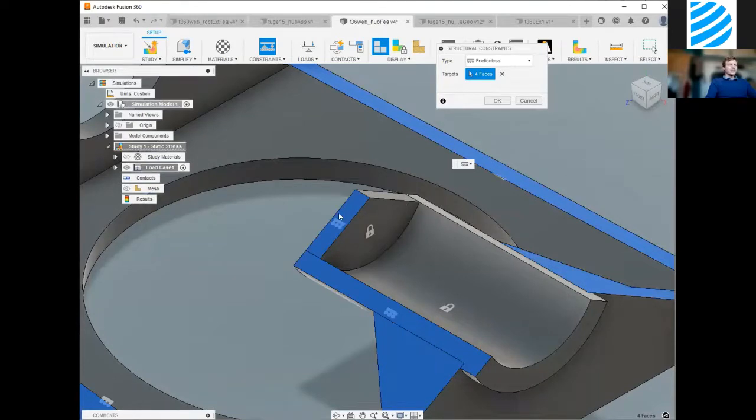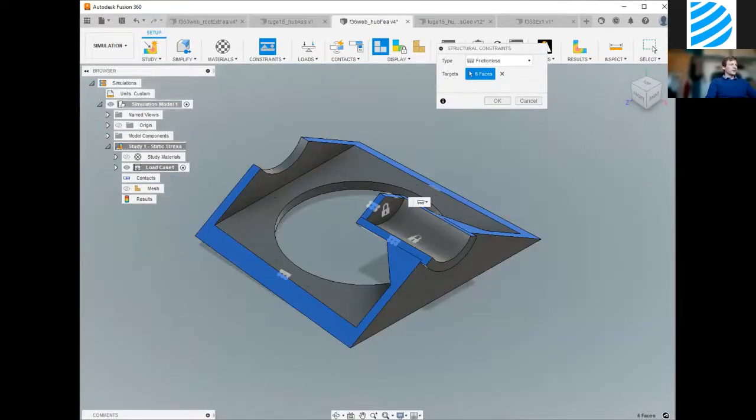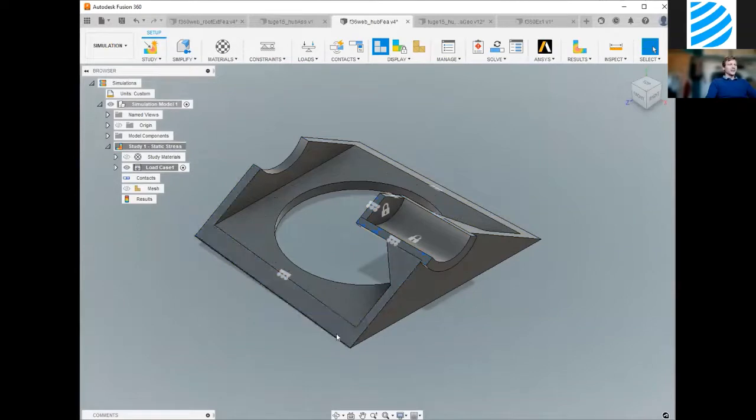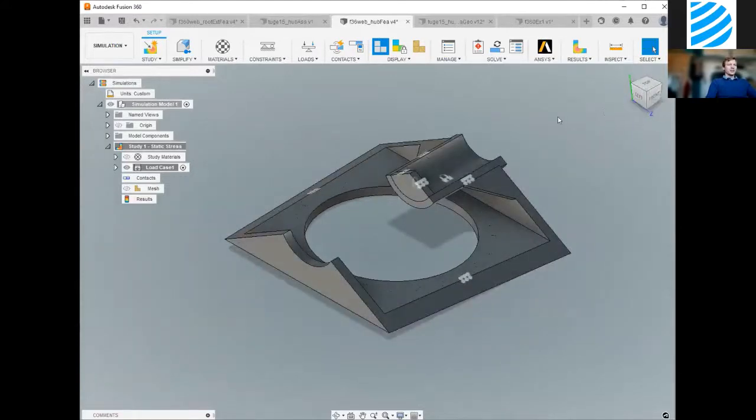What a frictionless constraint does is it prevents the surface from moving or deforming in the normal direction relative to the surface, because obviously there would actually be material there. It would be continuous all the way around. So this takes care of that. And beyond that, you would just follow the same steps we already followed with the other one, so I don't think I'll repeat that. I think our timing is pretty good now. And at this point, I'll just say thank you, and happy to take any questions anybody might have.